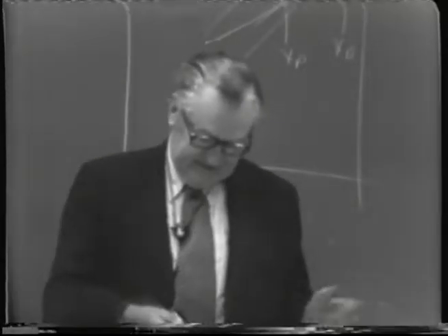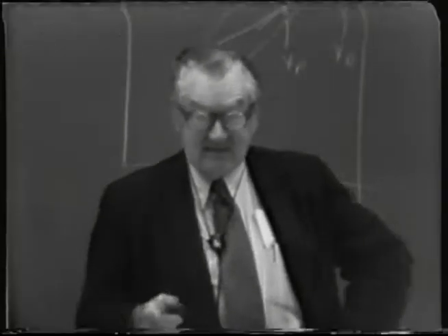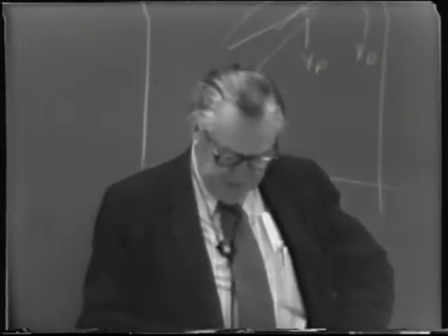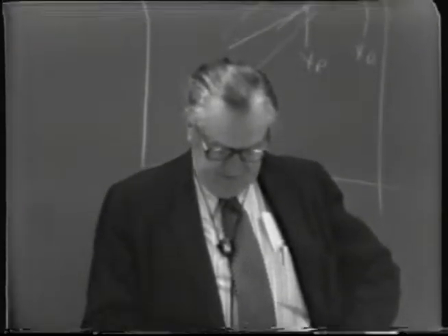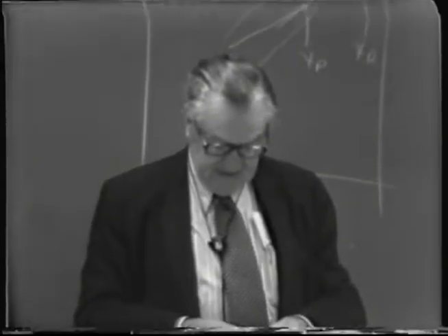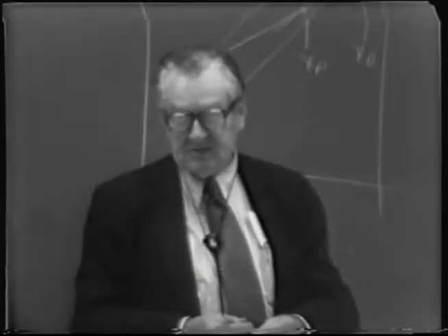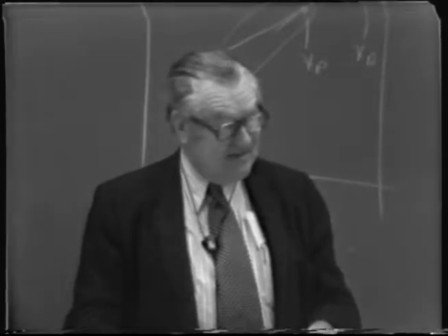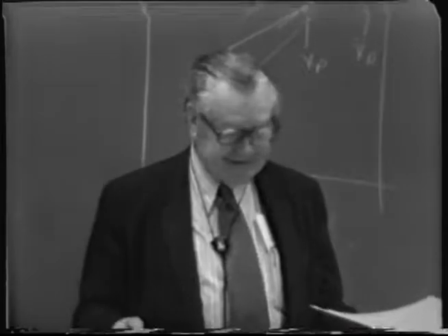This is a little bit indefinite, but anyway, it's essentially where I've got it there. So it appears that you need about a total of 20 steps to get down to this specified bottoms concentration. So that's the answer to the first part of the requirement, as I got it.